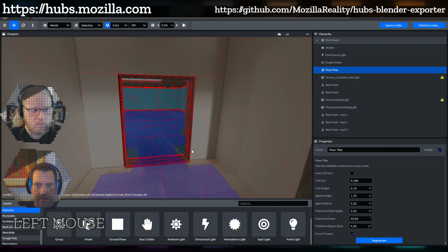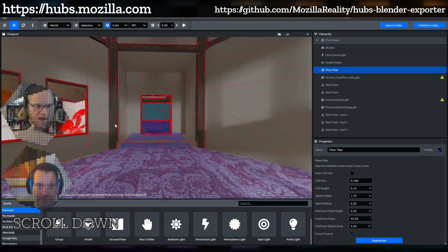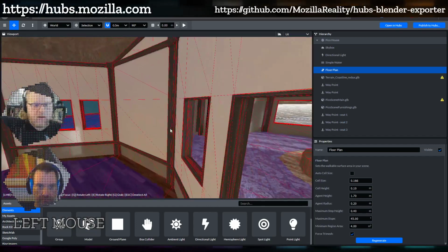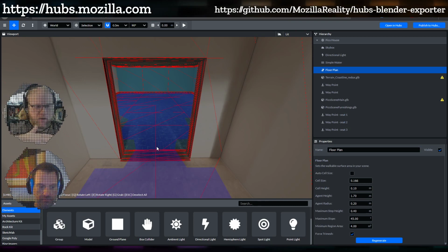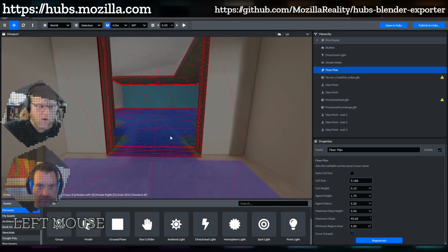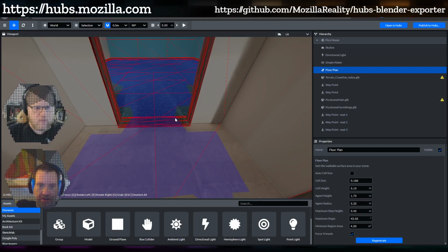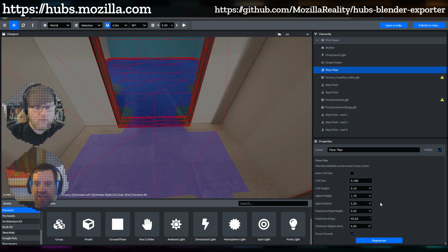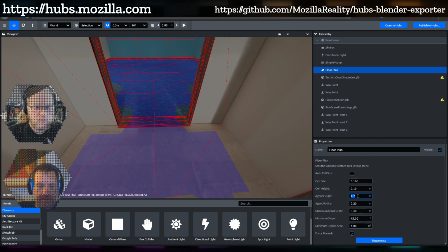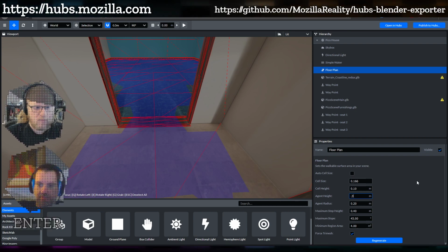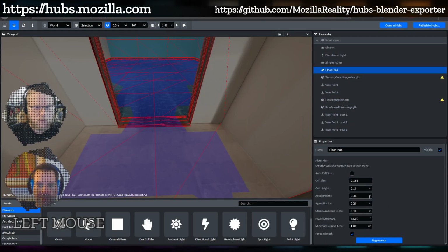Right, and this can affect things too. If you want to have multiple floors, that second floor has to be above this height. Otherwise, it's going to be considered part of the first floor, and then you're going to be overlapping, and the lower part won't have nav mesh, but the upper part will. And you go to teleport, and then you feel like you went through the ground to the lower floor or something. So if this agent height isn't high enough, let's say this was at 0.3 meters or something, and I hit regenerate, we might lose any connections in our doorways.